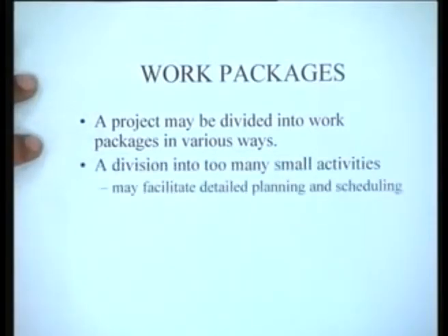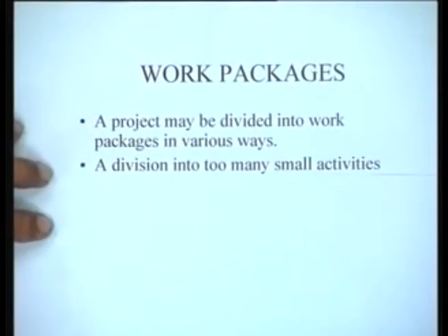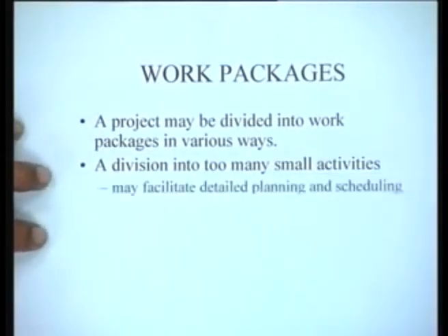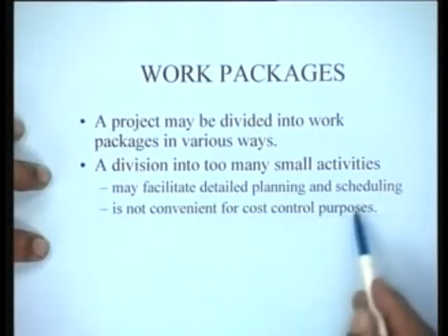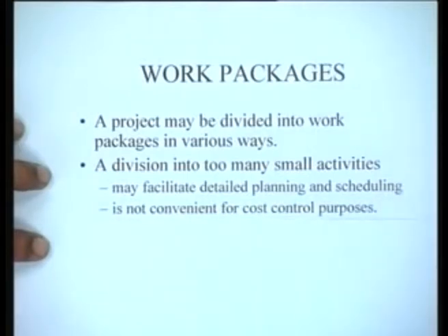So, it depends. In the same way, what would happen if we divide it into too many small activities? A division of the project into too many small activities may facilitate detailed planning and scheduling, because you now have detailed jobs which specify exactly what has to be done. From that point of view it is beneficial, but it is not convenient for cost control purposes. Why is it not convenient? Obviously, because if you have a project whose total cost is 1 crore and you have small activities which cost 8 annas, 1 rupee, 2 rupees, the number of activities will be phenomenal, and keeping track of all those activities would be an enormous job in itself, and therefore accounting would become very, very difficult, isn't it? So, it is not convenient for cost control purposes.